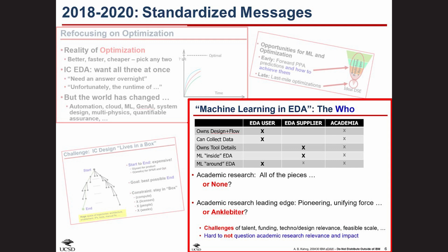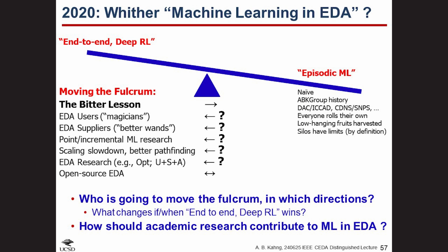And this is too busy, but this slide, if you download it later, shows how a human would make sure that routing succeeds, given a placement. The human would run the router, look at the result, handcraft routing blockages based on the violation markers, and iterate. So running the detailed router for an hour and a half, multiple times over and over.